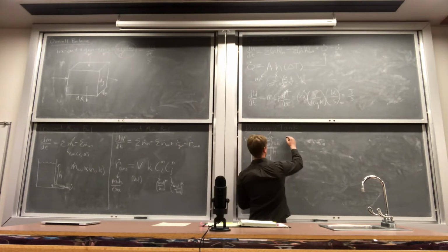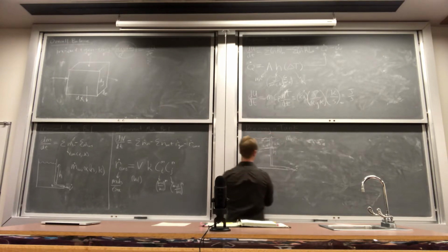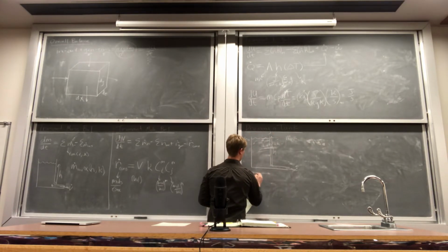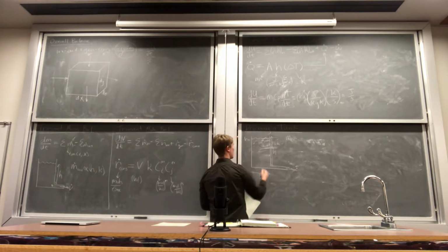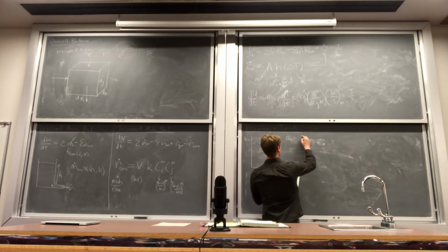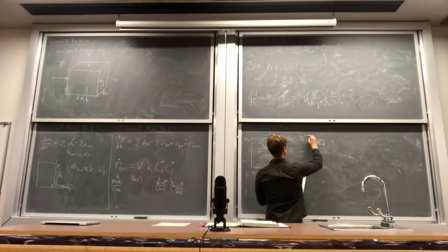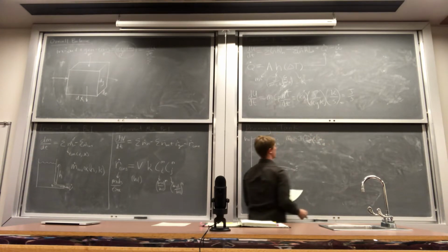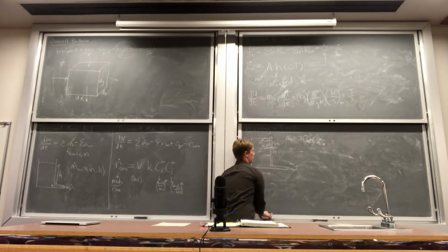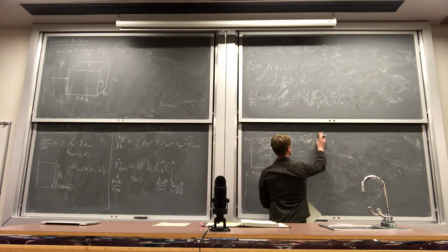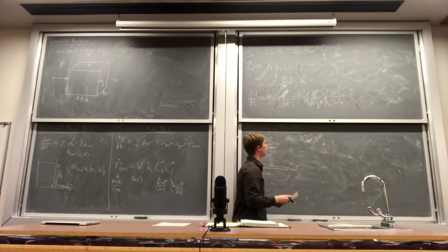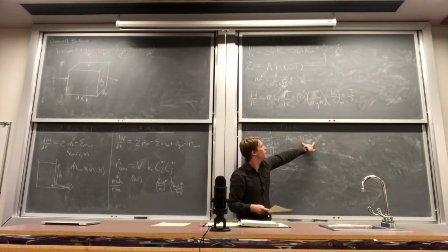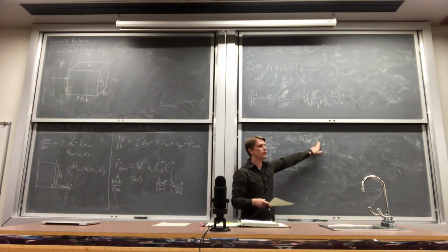So the initial mass, I'll call it m naught, is going to be equal to, let me draw it out here, the tank diameter. We have a tank diameter, we have a height, we'll say it's a cylindrical tank. π (d/2)² times ρ h naught. This is the volume of the fluid initially, and this is the density.